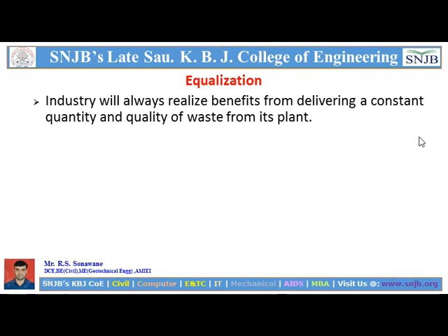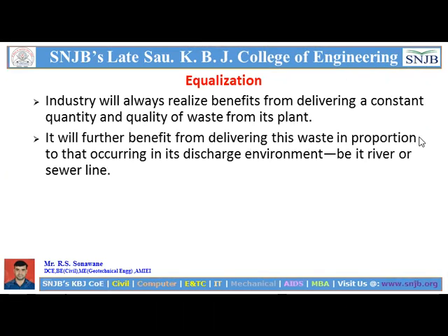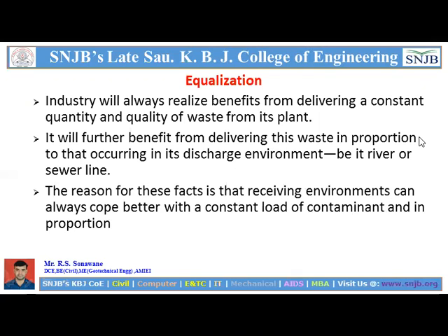It will benefit further from delivering this waste in proportion to that occurring in its discharge environment, be it a river or a sewer line. The reason for this is that the receiving environment can always cope better with a constant load of contaminant